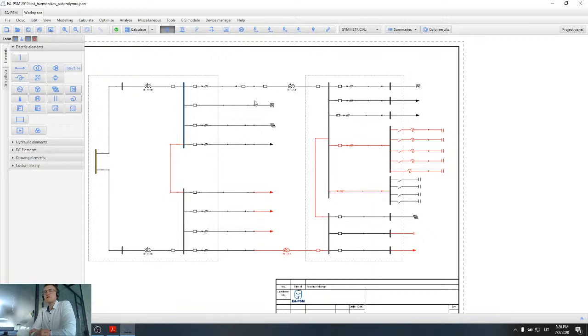This damages insulation inside the capacitor, and then we have a short circuit inside the capacitor. Short circuit usually has high current, which is actually the main cause of explosion of the capacitors.